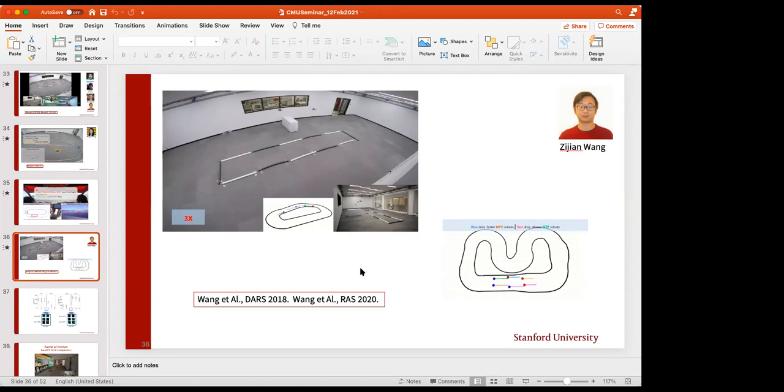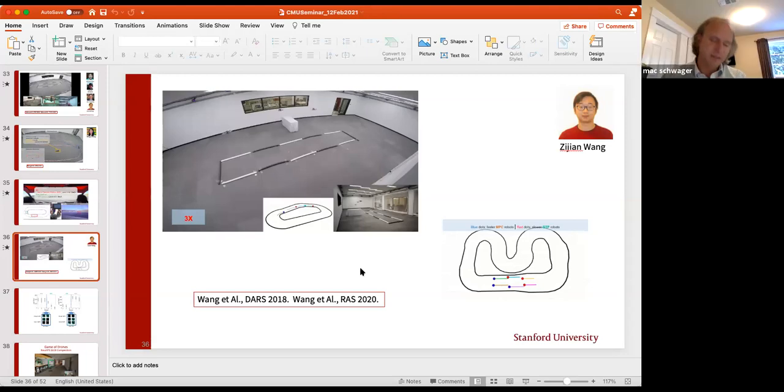But just to follow up, that also assumes that other robots allow you to access their state. Well, to a certain extent. I see your point. By states, let's be a little bit careful. There's the current state of the robot, and then there are the optimization variables. We don't need to know their optimization variables. We're solving internally to predict what their optimization variables might be. That's the intention inference piece. But yes, we do need to know their current state, at least their current position or pose. And we assume we can do that with onboard sensing or some onboard estimator.